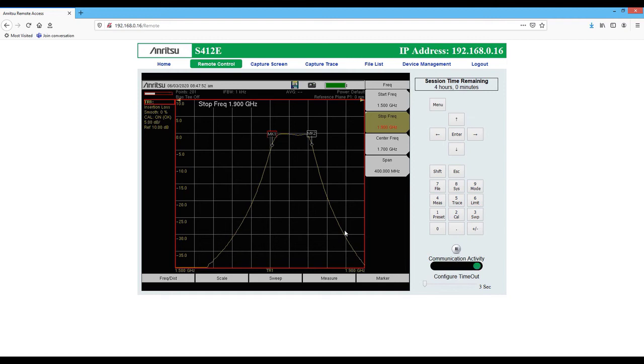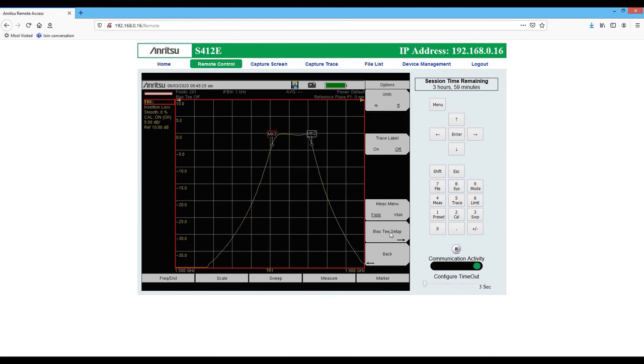For those who are familiar with VNAs, VNAs use what they call S parameters. S11, S12, S21, S22. Now, this is not a full reversing 2-port. It is a 2-port, 1-path VNA. So I could go into the System menu, just like I do for many other things. But instead of going into System Options or anything, I go into Application Options.